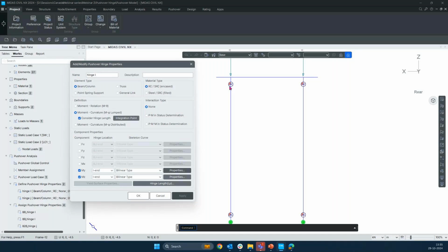But if you are modeling a global structure which has multiple bends, then there could be redistribution of load when a plastic hinge is formed at one particular location. So it is very important that if we are using a global model in the analysis with multiple bends and multiple probable plastic hinge locations, then we shall consider the PMM interaction to determine the accurate computation of the plastic hinge mechanism in that particular structure.